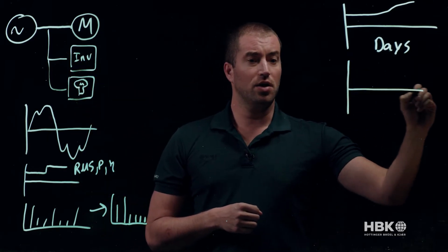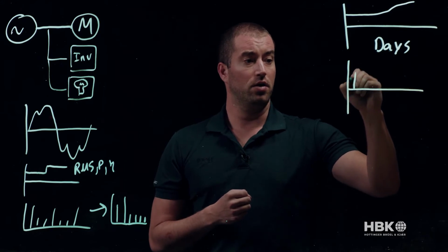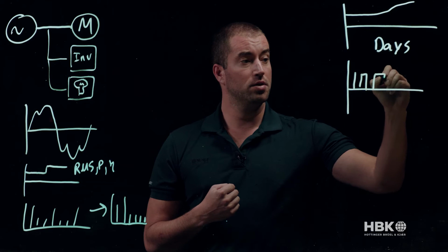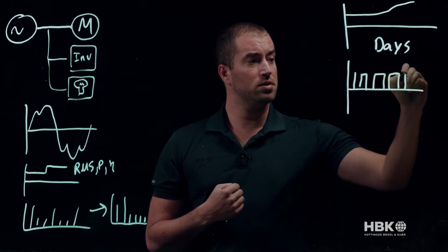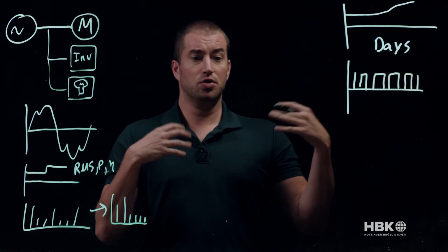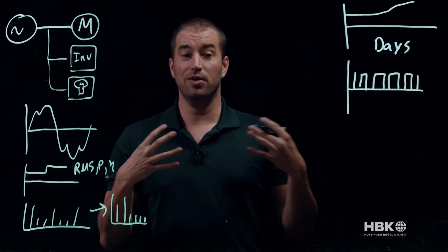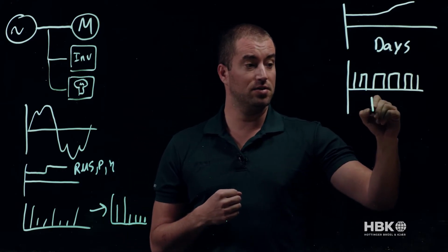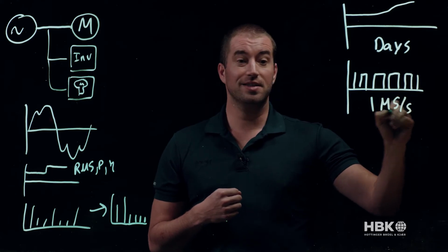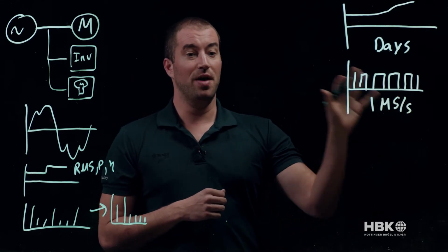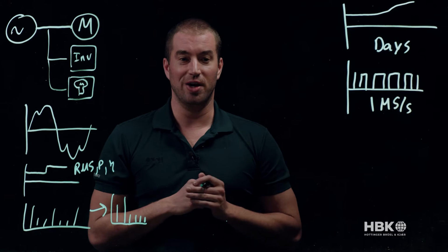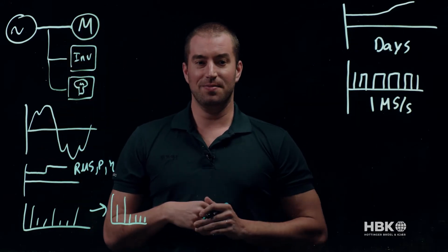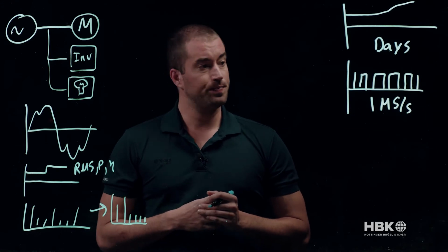So our inverter loads are often powered by a PWM voltage. These PWM voltages are switches that are turning on and off at the kilohertz rate. To understand that, we often need to measure as high as megasamples per second. Now you can imagine measuring a variety of channels, maybe on a variety of loads, for days at megasamples is an unreasonable amount of data.